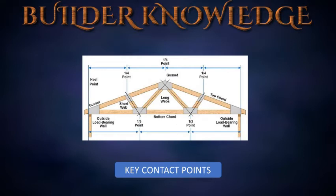Layout for a W-type truss. The W-type truss demonstrates key contact points of the webs and cords to properly distribute the forces acting on the truss. Also shown are gusset cutout sizes and nailing patterns for nail gluing. The span of the truss, depicted in the slide, is 26 feet and roof cut is 4/12. When spaced 24 inches apart and made of good quality 2 by 4 inch members, the trusses should be able to support a total load of 40 pounds per square foot.